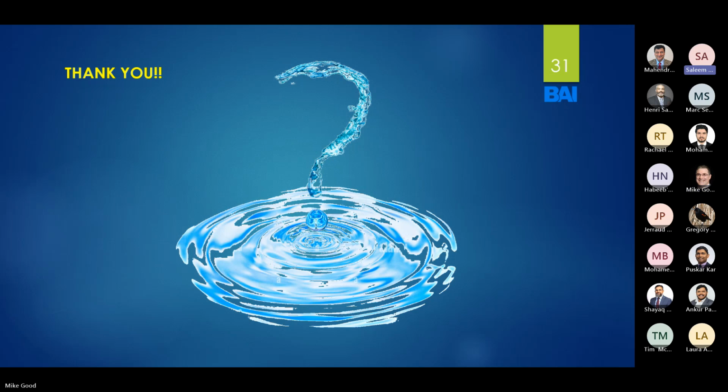So it is possible. I'm not saying it could have happened, but it is possible that 39 feet, maybe 37 feet or 41 feet, might have occurred during the high velocity zone. But as the hydrograph descended, the flow velocity got reduced. Whenever flow velocity gets reduced, it means it is depositing sediment. So there was scour, and then afterward there was aggradation there.